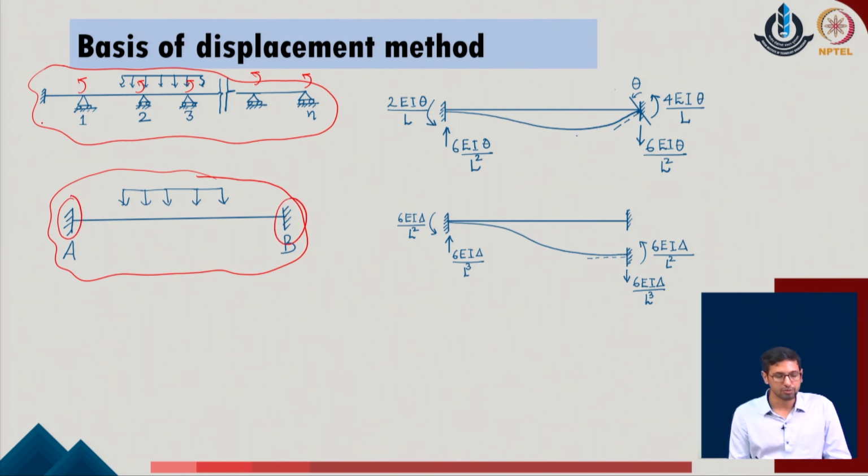So now when the question comes up to define the kinematically determinate system for this original problem, we have a unique choice because we restrain all the rotations of the given system which are free to take place, and while doing so we will generate a system having all the joints fixed in the given problem.